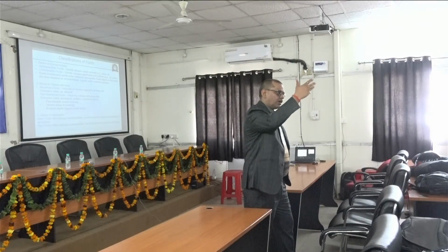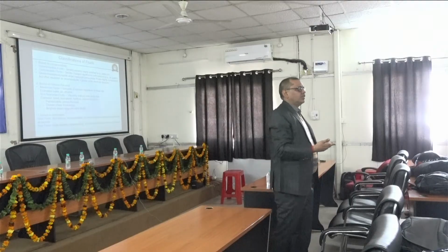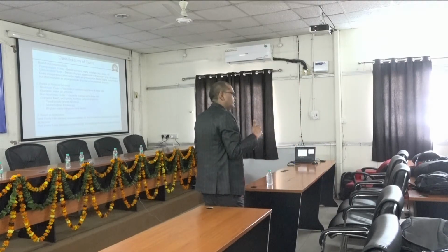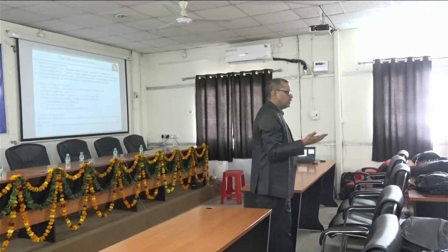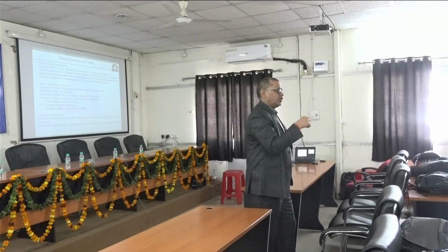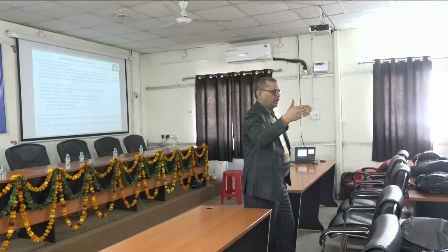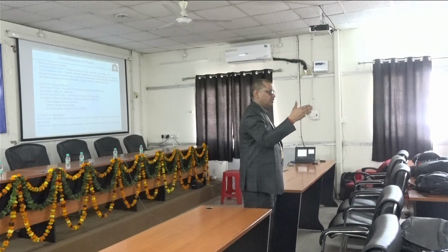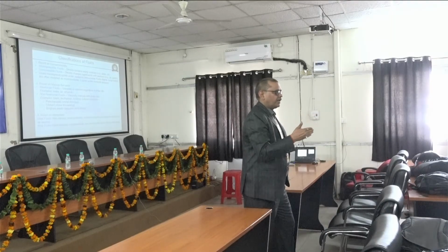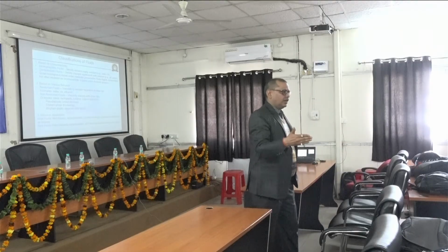So when you consider all cases together, that model is known as the power law fluid model. The power law fluid model is a non-linear model because it is mathematically non-linear. That's why tau is equal to mu gamma dot to the power n is non-linear in nature. So based on the viscosity, based on Newton's law of viscosity, you can categorize fluids as Newtonian fluid and non-Newtonian fluid.